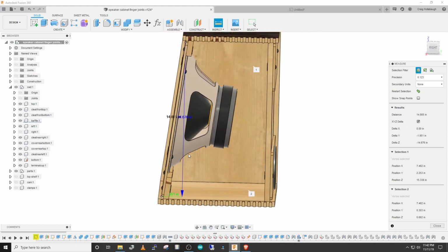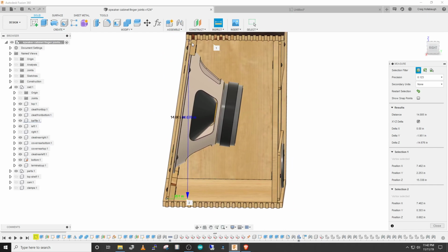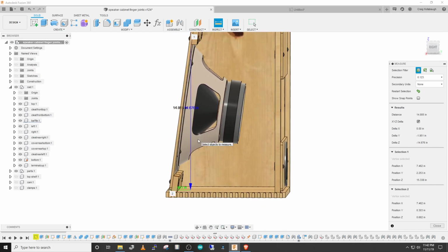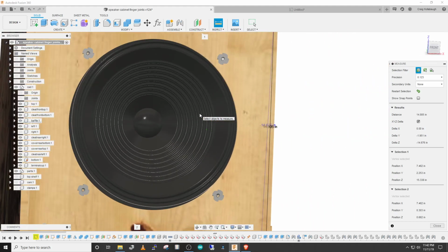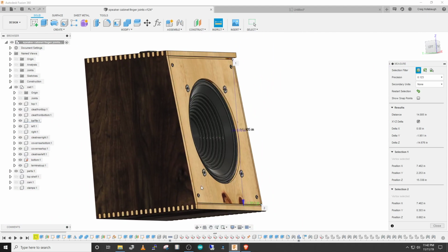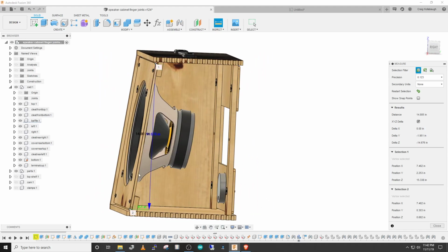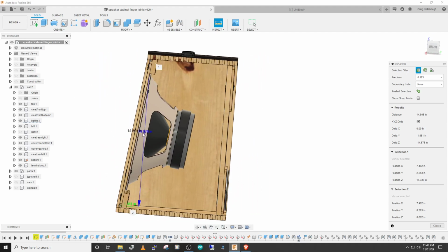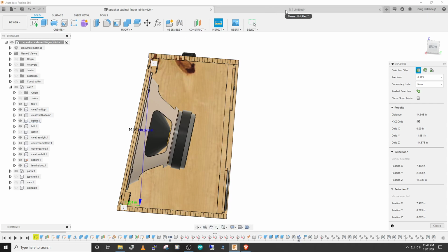What it's really measuring is the distance of this piece as it is projected onto the plane in the drawing and giving me that distance instead. This gets a little more severe if I change the angle of the angled plane by changing the top depth. Then the actual baffle top to bottom distance gets taller, gets longer, because it'll be over like at an angle like this, but this distance here will be about the same.